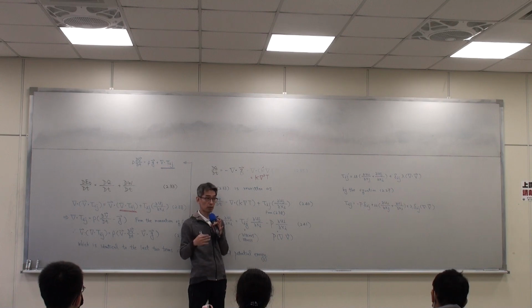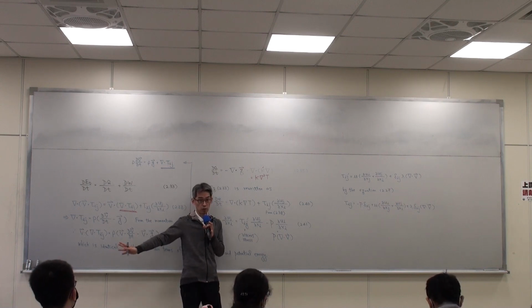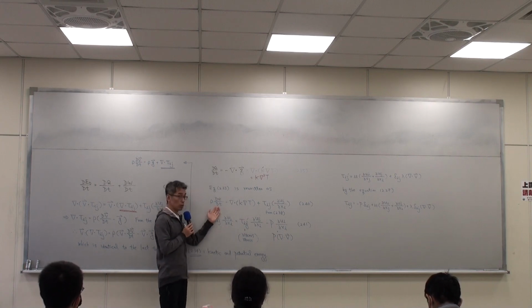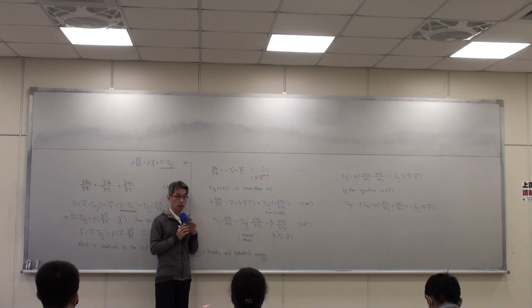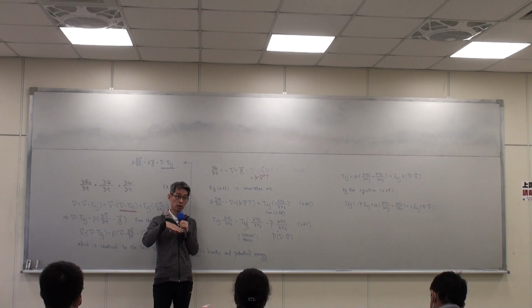So that's why the Bernoulli equation reduces its useful energy later on downstream. But the energy cannot disappear. So this energy will become internal energy. That will become thermal energy. The thermal energy cannot completely convert back to mechanical energy.